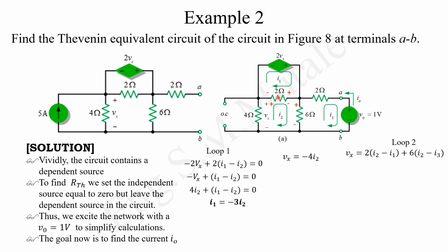The voltage drop there is basically this resistance, which is 2, and then depending on the current. So this current is entering from the positive, that's why you have positive I2. That current there is entering from the negative. We are in here, so positive is here, negative is there. So this one will enter from the negative there, that's why you have got negative I1.